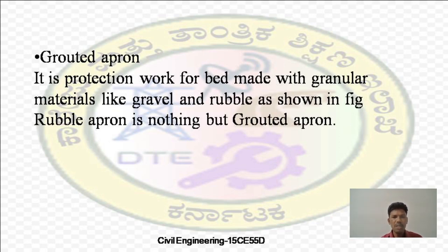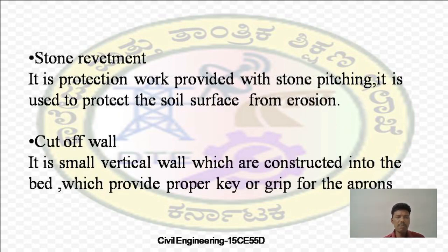Okay, stone revetment. It is the protection work which is provided with stone pitching. We provide stone pitching on guide banks and then river training works, the purpose being to protect the exposed earth surfaces. Wherever the surfaces are exposed, we provide stone pitching protection work, and that can be called a stone revetment.